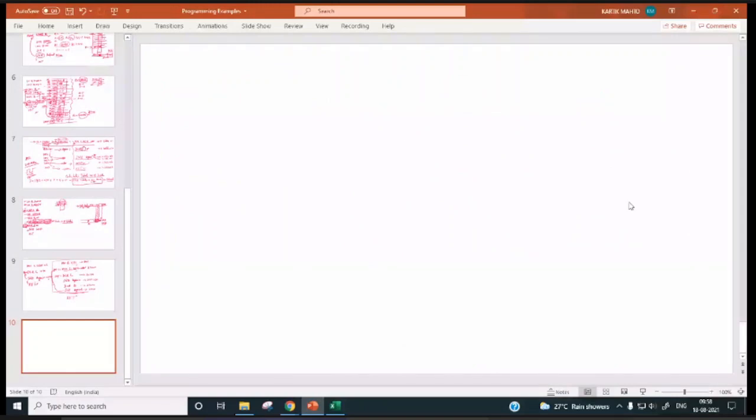Now I am writing another delay program having two registers, but the instructions I am changing. Now I am writing LXI B, 0346H. Now we can write, say, the instruction DCX B. So now the BC pair will be decremented by 1. BC minus 1.